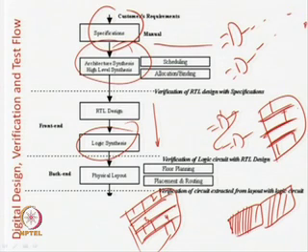So, you have a big box and you have different sizes of oranges. How will you arrange the oranges in the box so that the maximum number of oranges can be placed in it? Same thing here. There are some rows, and some gates will be this thick, maybe your OR gate will be this one, the XOR gate will be longer and the inverter will be thinner. Generally the height is the same, only the width varies over a very broad spectrum. So, very broadly speaking, if the gate takes more area, it will be long in this direction.